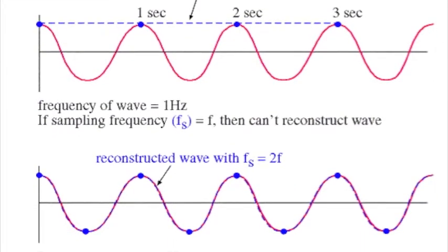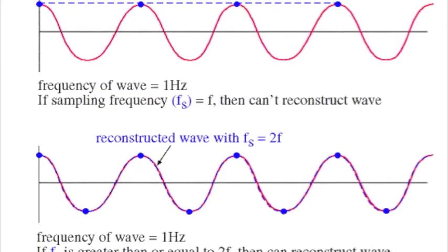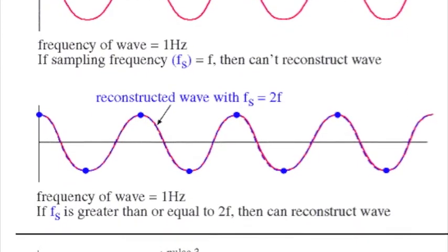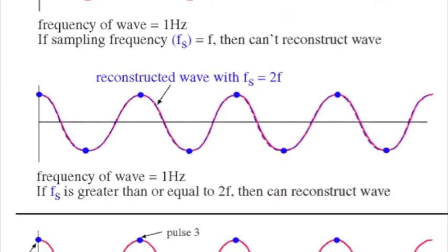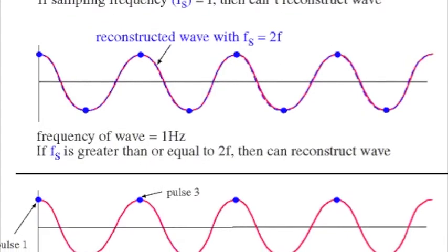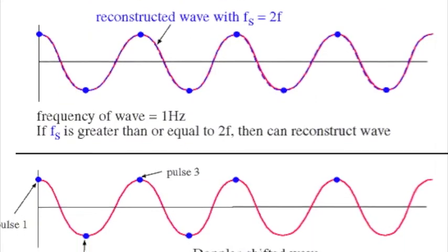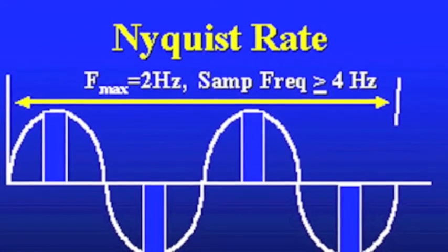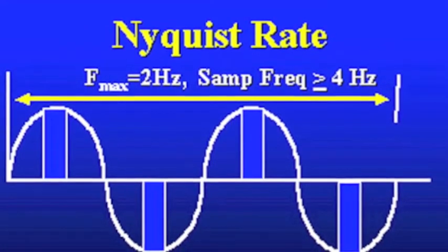Two important concepts in data acquisition are Nyquist frequency and aliasing. The Nyquist frequency is half of the sample rate and must be greater than or equal to the frequency of the highest frequency component of the system in order to ensure accurate data acquisition. As a result, the sampling rate must be at least twice the frequency of that component.